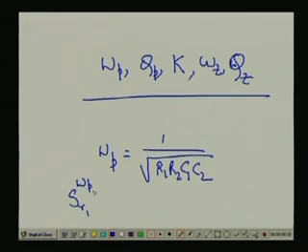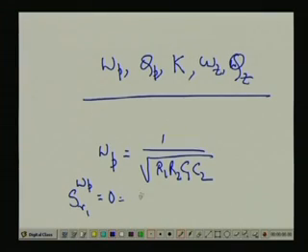That is also there in the case of positive feedback topology. Since it is not there, if I vary small r1, how much will our pole frequency change? Nothing, is it not? So it is obviously 0, and similarly for S omega p with small r2. Clear? This is our sensitivities figure.